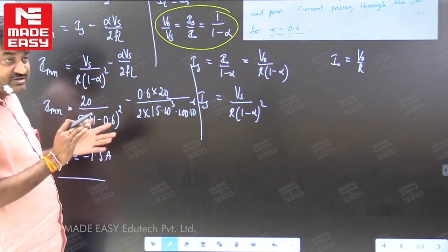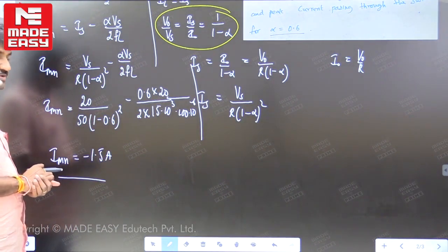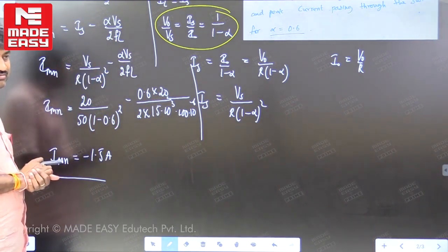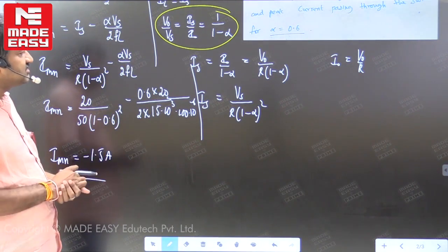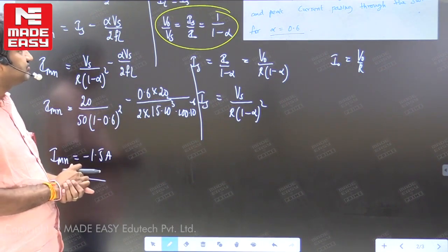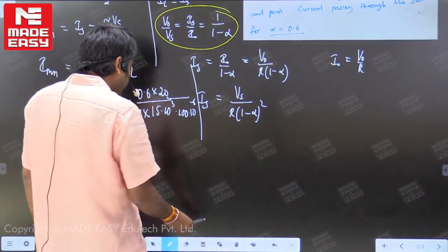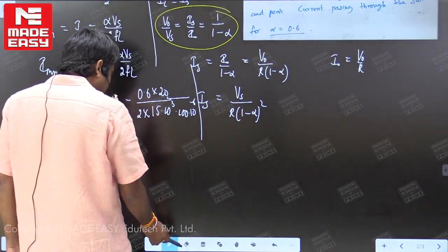If our assumption is right, I minima should be positive, but I minima is negative. So the assumption we made is wrong. If it is not continuous, it should be discontinuous or at the most at the boundary. So I hope that it is a discontinuous conduction here. If not discontinuous, it may be at the boundary. These are the two options we have.